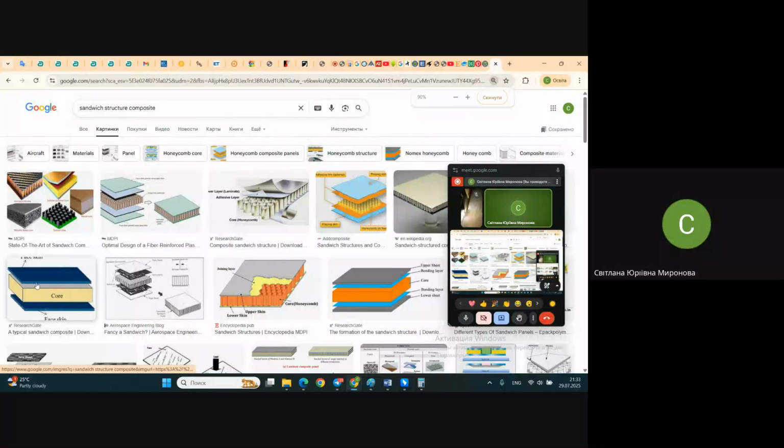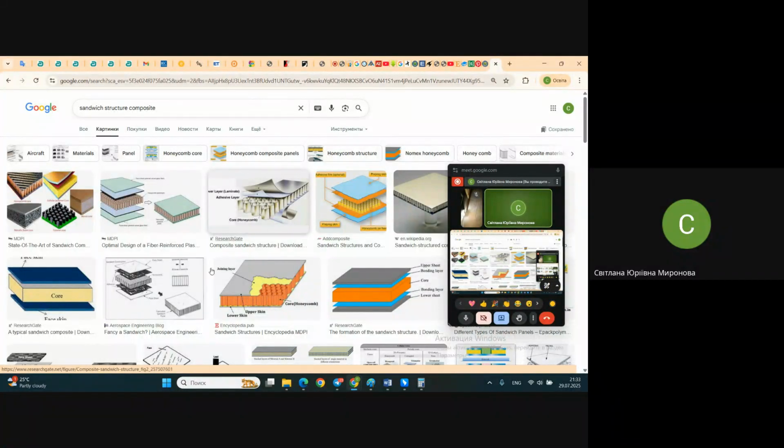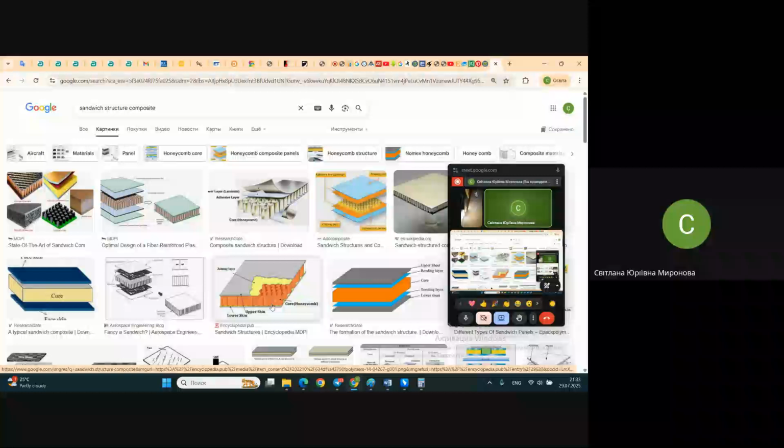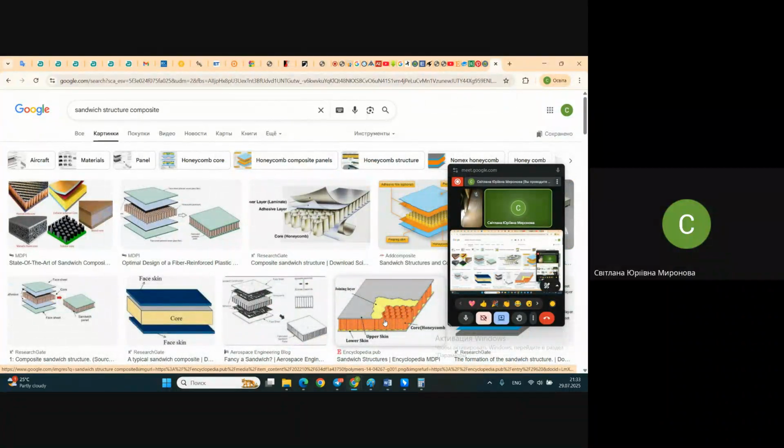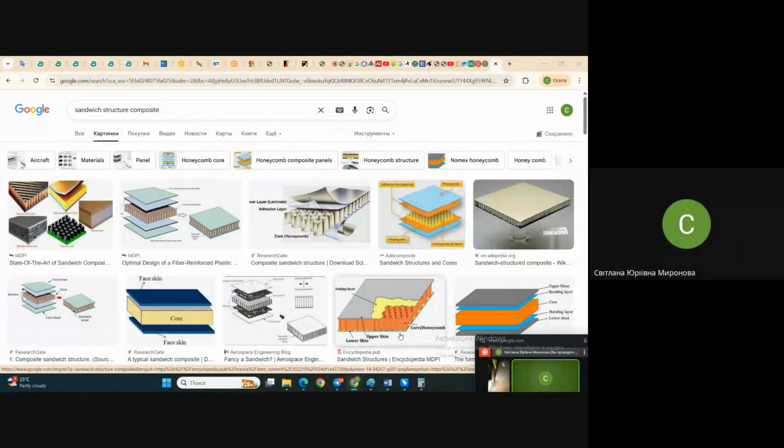You see, this honeycomb structure is altogether very thin, like foil, with a layer of skin at the top and at the bottom, and these honeycombs are made of very thin, very delicate materials. As I said, it may be metal foil, it may be composite material, it may even be special polymeric paper. Each element is extremely delicate and you may break it with your fingers.